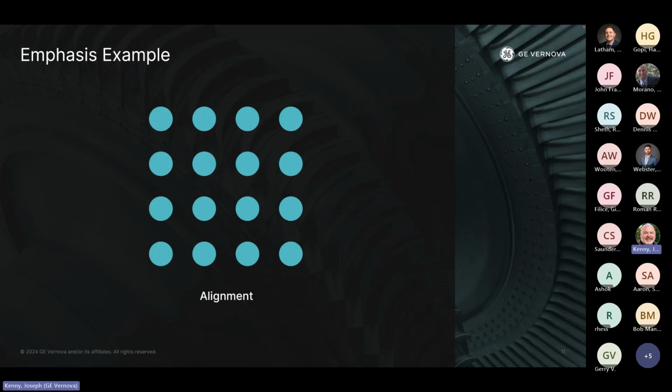Another thing that I just like to show, and this is just a very high level design example, is that alignment is really, really important when you're doing design. So when you're laying out your high performance HMI and you're doing your different components, laying them out not necessarily how they exist in the real world and mimicking exactly what's in the real world, organizing them in a scannable fashion can be more useful to the end user than actually what it might look like in front of them.